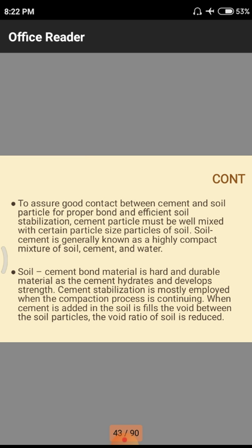After that we have to add the cement and we will get the strength. So we have to observe first and then confirm whether it is good or bad. If the soil particles are very fine, automatically those are not sufficient. We have to observe three grain types: coarse grain, medium grain and fine grain. Very coarse is not suitable, very fine is also not suitable. Only medium grain size particles have the capacity to bind together with the help of cement and water content. So we have to choose these medium grain size particles, then only this cement stabilization will get strength.